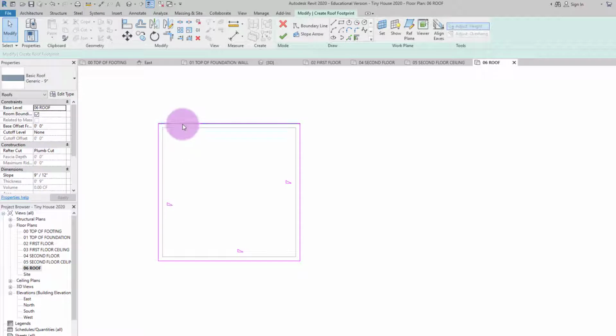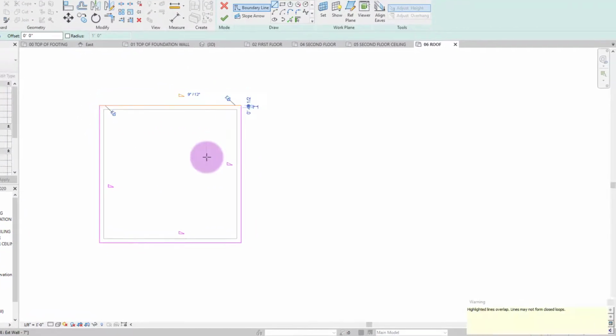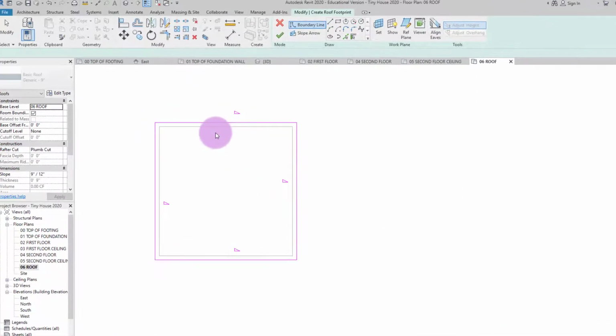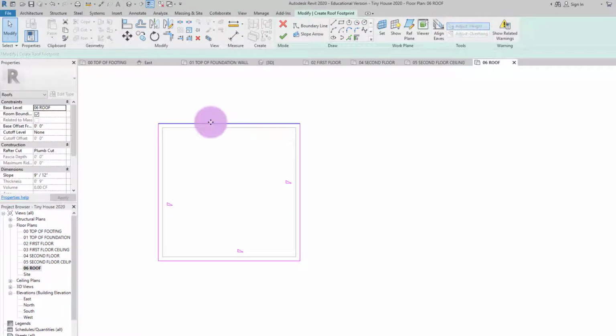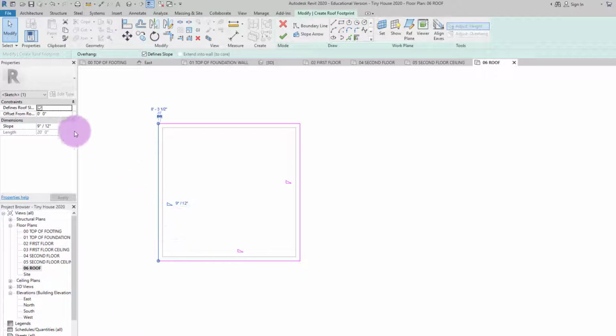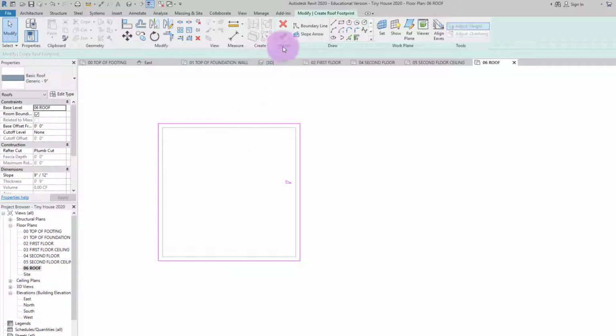And that's another point. Make sure if you draw on top of lines, like watch this, you'll get this error and you can't really tell either that you did it. It's just like AutoCAD, you can't tell if the lines are on top of each other. And you can't finish the geometry. The geometry needs to be complete without any overlapping lines. So just be aware of that. So we're just gonna play around here for a second, and I'm gonna show you what's gonna happen when we turn all the slopes off except one.